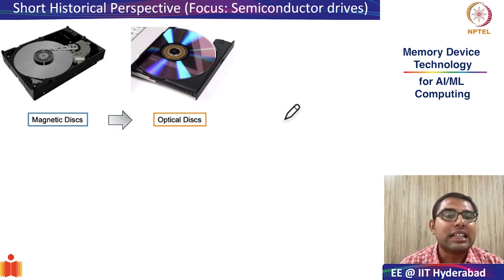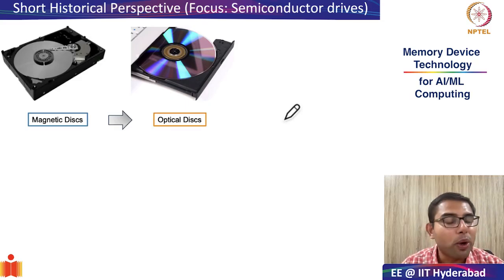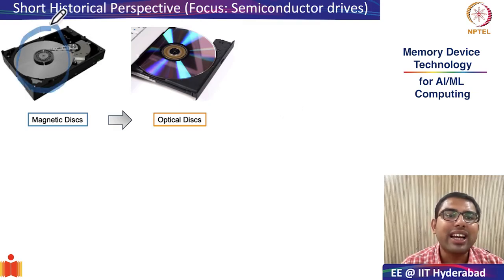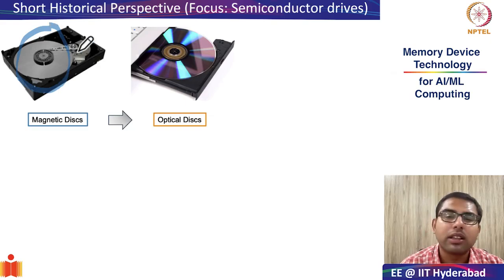As you may know, the main storage element for computing systems, which is still used in some servers and some low generation computers and even laptops, is something called magnetic disks. The magnetic disk is a very simple device. By switching the magnetic polarization from a read-write head, which is a mechanical read-write head, you are able to write bits into this magnetic disk. The principle is the same as the old gramophones that we might have seen in the movies.